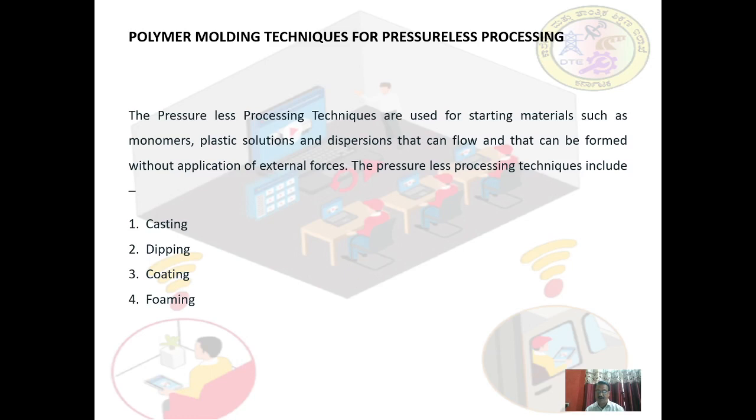In this method of casting, polymer solutions, melts, or dispersions are cast directly onto a metal drum or a rotating belt, and from the slot die into a precipitation bath. Slush molding enables the production of hollow articles which are made from PVC pastes.